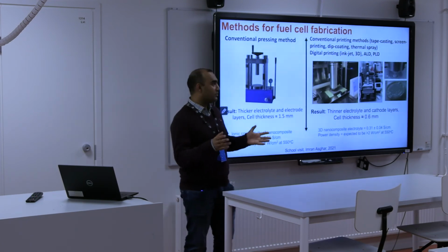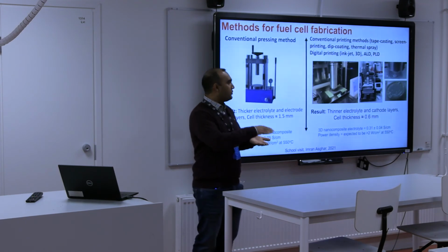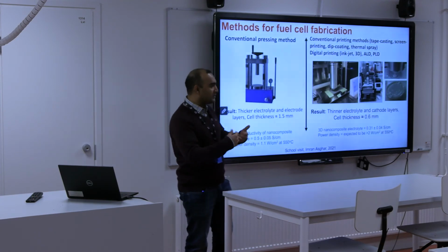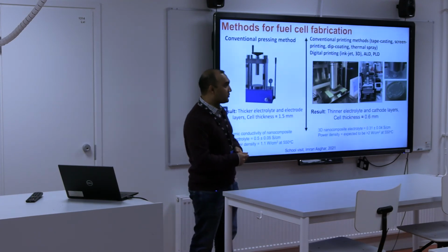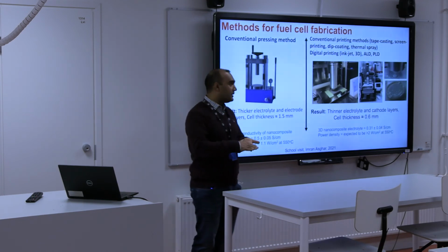These are physical vapor deposition techniques where you make layers by atomic deposition. Of course, it's easy to say than actually do it. There are lots of research questions there. But with those techniques, we can make very thin layers, and I'm talking about hundreds of nanometers.